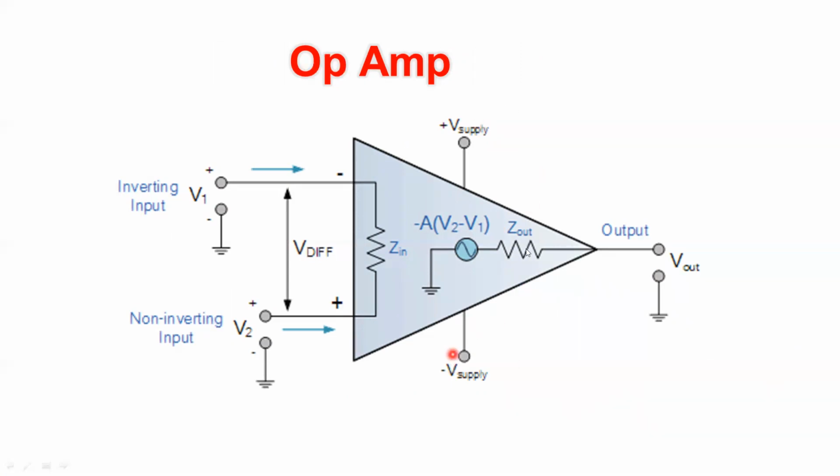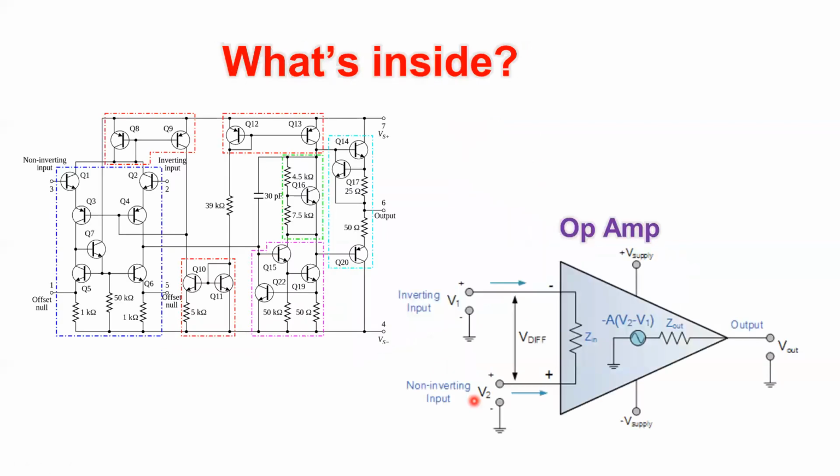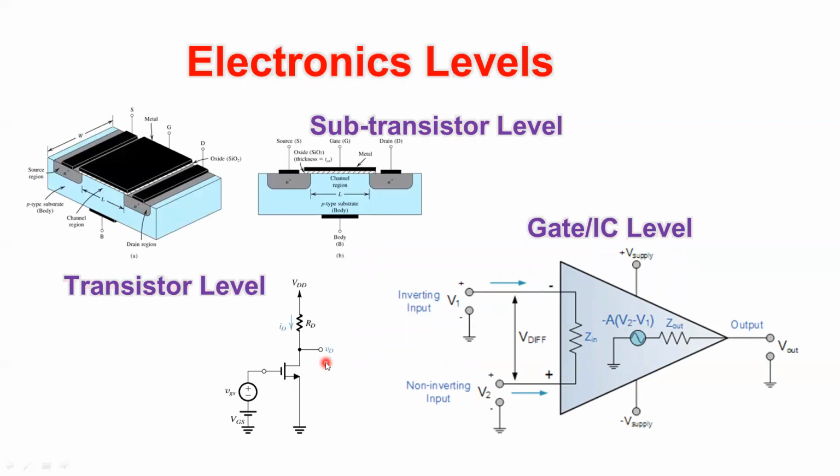First, we have what we can call the biasing terminals or the supply terminals. These are the supply used to operate the device, to operate the transistors inside. To make this clearer, let me return to this circuit. I believe you already studied this circuit in lecture number 2 on the MOSFET. Here you have an input and here you have an output. But in order to make a relation between the input and the output, a DC biasing is needed, what we call VDD, which is a voltage applied to the drain through the resistance. Without this VDD, you will not have this input-output relationship.